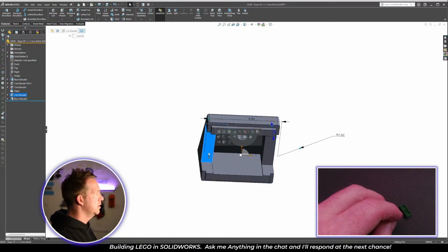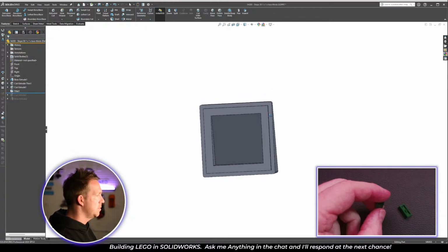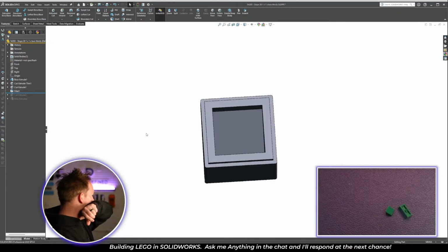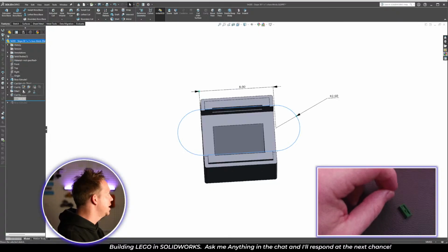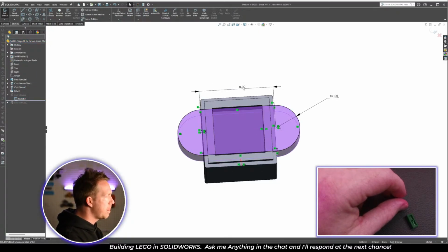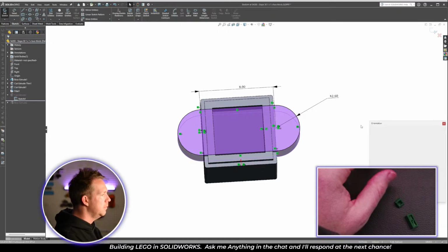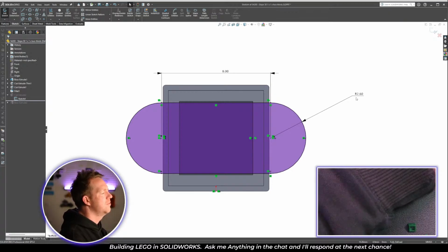Let's see this cut. It's going all the way through. If I remove that, how does that look? That part looks much better. This cut needs to just change to a circle in the same position. So it's going to be a 5.2 diameter circle.